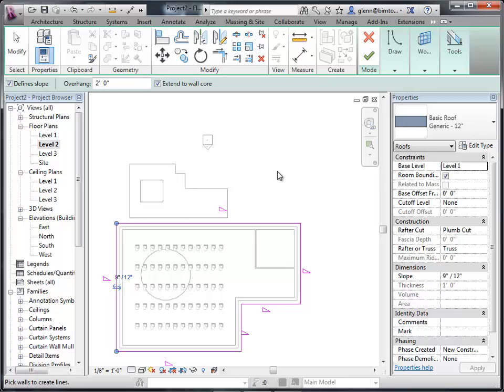People want those. A lot of modern architecture has very shallow roofs. When we were building a lot of the ranch houses in this area, it was either 4 to 5 inches. If you get to the Case City houses, all the mid-century modern stuff, those would be 2 and 3. It was really very shallow. So it's an architectural style statement about what you want to be.